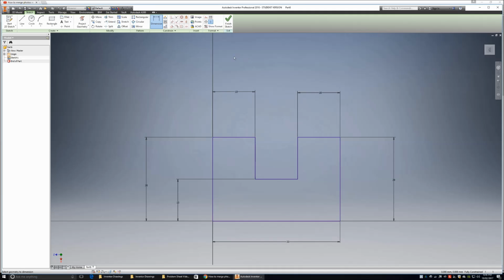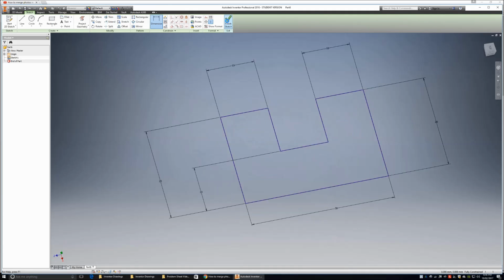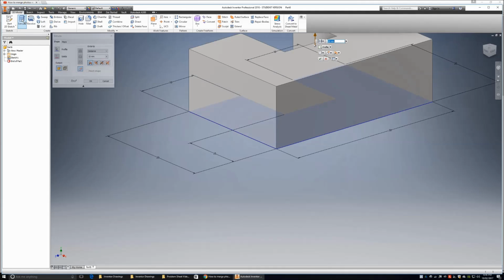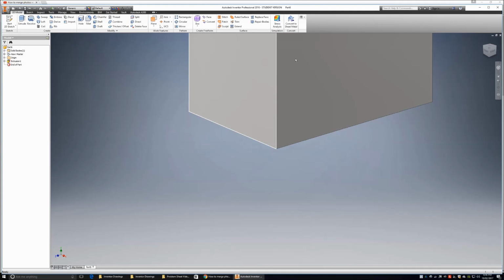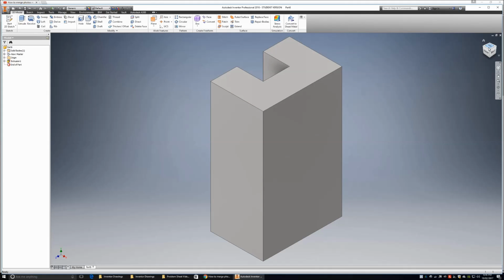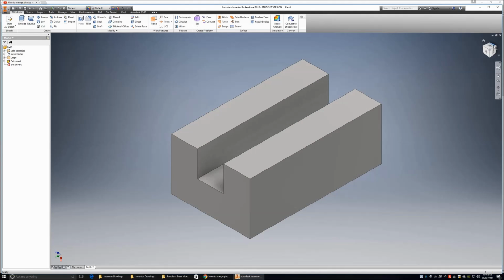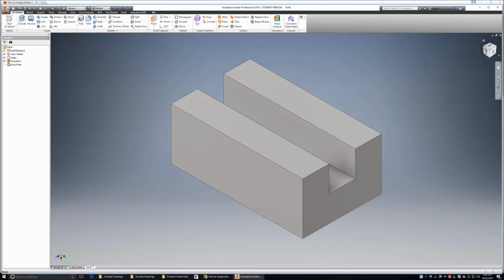It's the right profile. We'll finish the sketch. We'll go over to the top left hand corner and extrude, and extrusion is 50, so type in 50, enter. Come back over to the right hand side to our block and click our corner icon again so we can see it. Click on the top. Yep, that looks pretty good. That's what it looks like to me, and just checking a few other sides. That looks the same as what my drawing is, so I'm pretty happy with that.